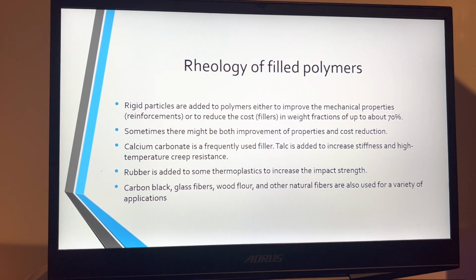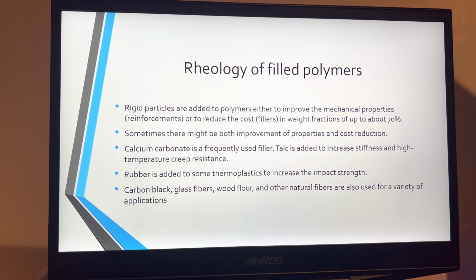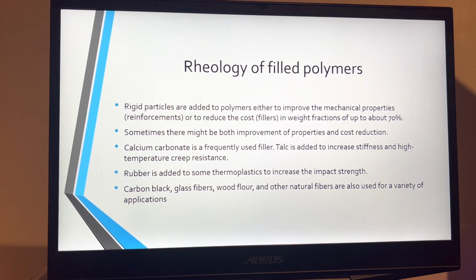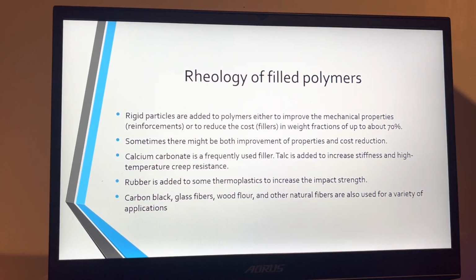Rheology of filled polymers. Rigid particles are added to polymers either to improve the mechanical properties, as reinforcements, or to reduce the cost, as a filler, in weight fraction up to 70%. Sometimes there might be both improvement of properties and cost reduction.